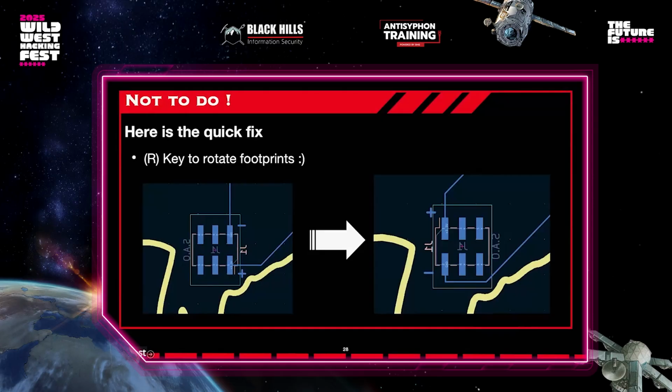I just have to rotate this one the other way, because when I added this one on the back, I just copy pasted, and it was the same rotation as the front. So the plus and the minus are not good. I need to flip that because on the host port here, I need to respect that order because the plus and minus are going to be in that exact same place. So if I solder a connector here, it's not going to be powered on because the plus and minus are here.